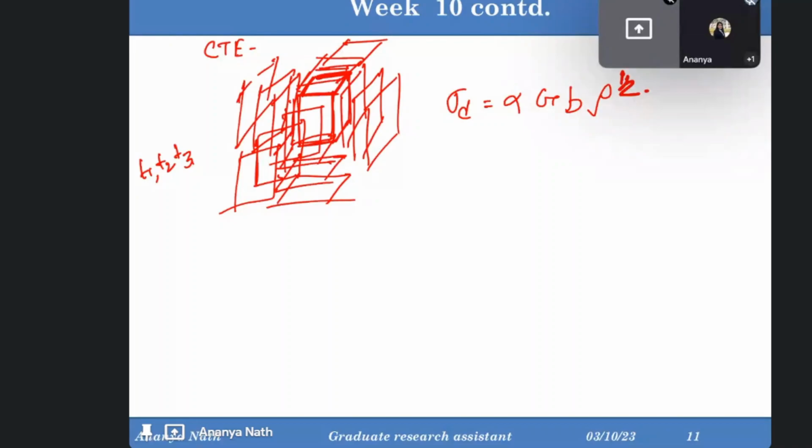Ma'am, this dislocation is punched out from the interface, because of the thermal stress generated due to the coefficient of thermal expansion mismatch, right? Yes. So the dislocation is being punched out from the interface, like these planes. Yes, these are the planes being punched out, just like a dislocation. These are punched dislocations. Okay.